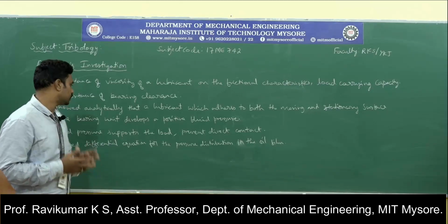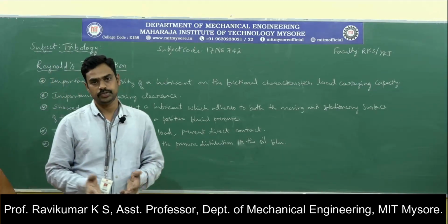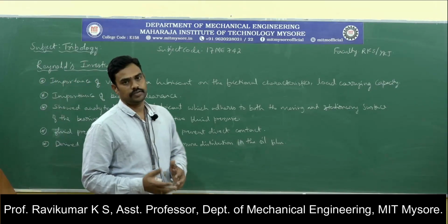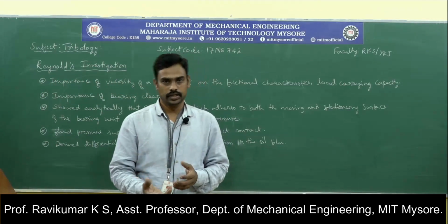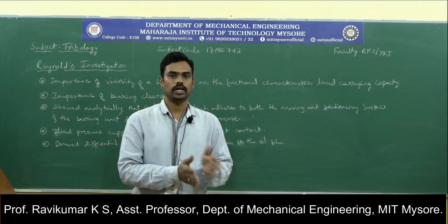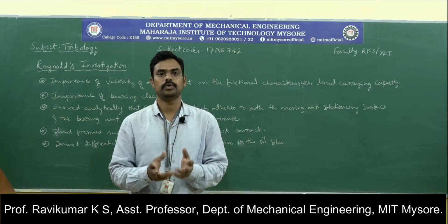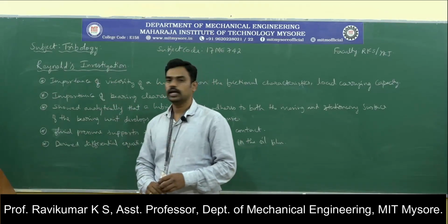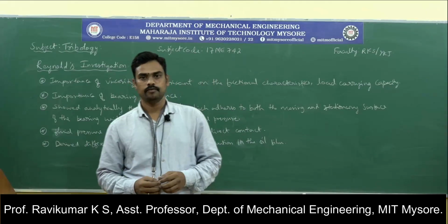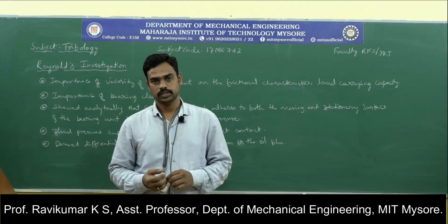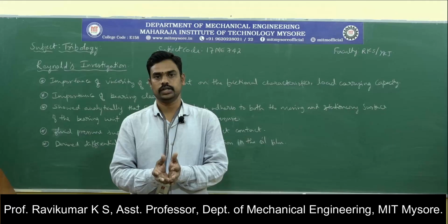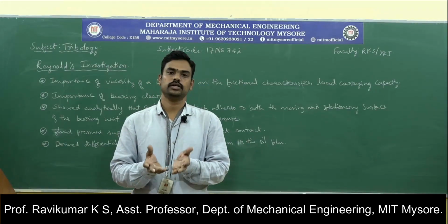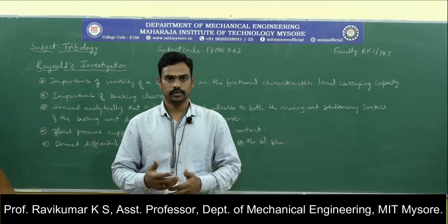Then he derived a differential equation for the pressure distribution in an oil film. This differential equation becomes the basic equation for hydrodynamic lubrication. So if you talk about hydrodynamic lubrication, the basic equation is the Reynolds equation. So with that equation, Reynolds concluded the experiments of Tower.